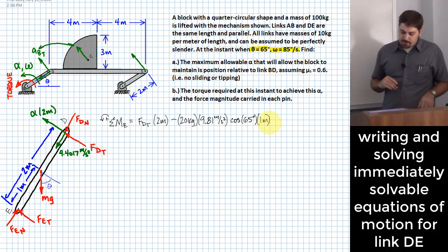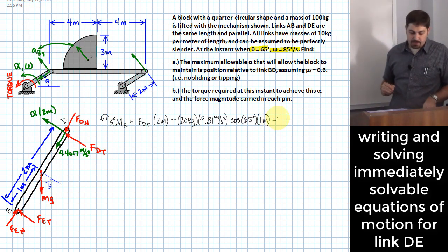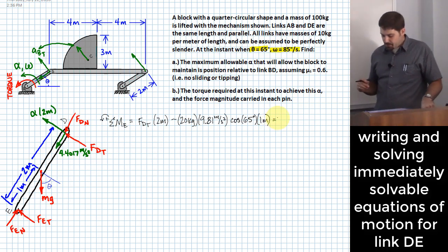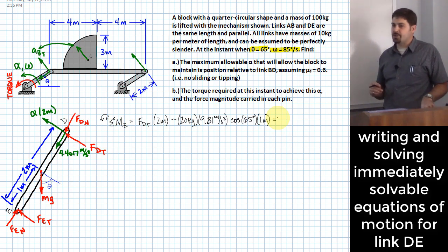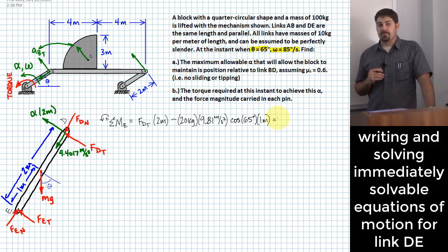Now I want to use another little trick that's helpful a lot of times. If you're dealing with a part that rotates purely, it is possible to figure out the moment of inertia around the axis of rotation rather than around the center of gravity. We did a problem like that earlier, I think. For a slender rod like this, that formula is given in the back of your book.